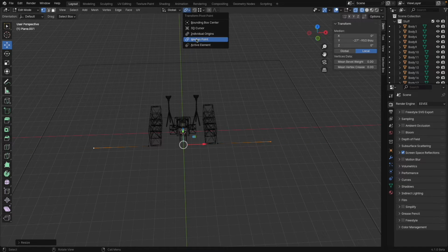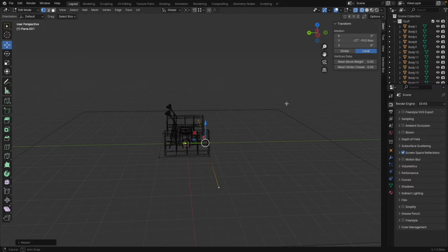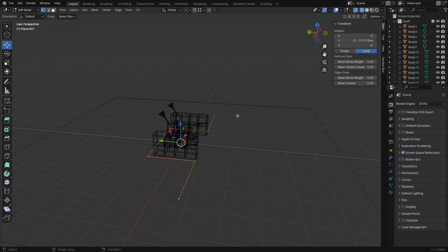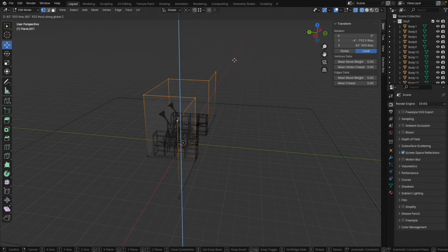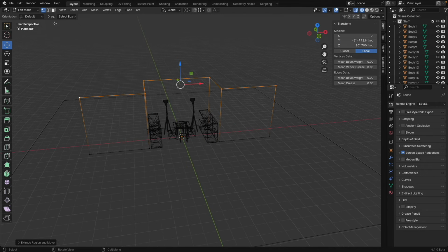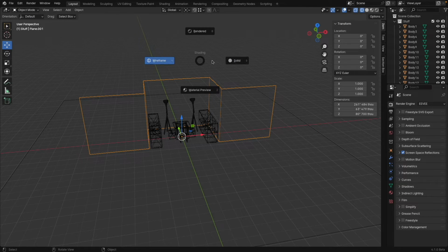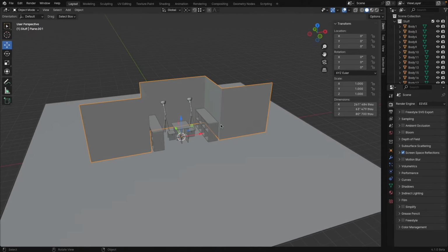I also have actually, for example here, this selected. No, this is just an outline. Press A to select all, E and Z to extrude this up to a believable height, like this. Beautiful. Z and solid view. Yeah, not too shabby. Now the wall's a little bit boring. We need an extra detail. For example, a baseboard. How can we do this? That's pretty simple.